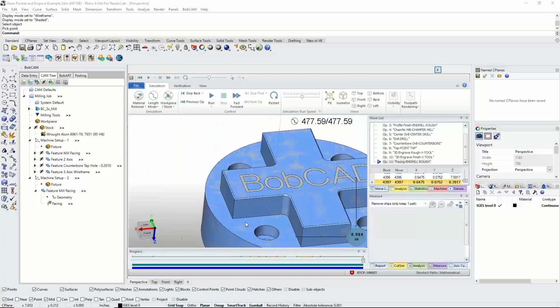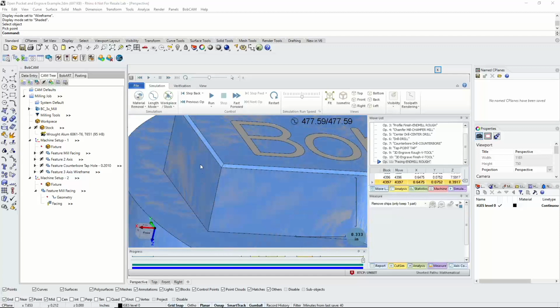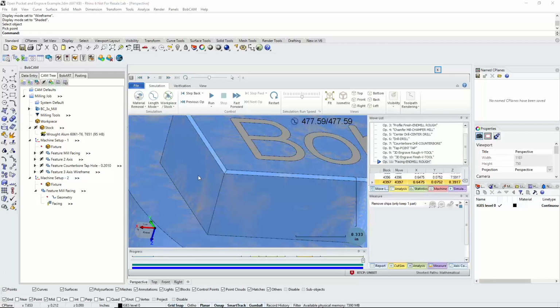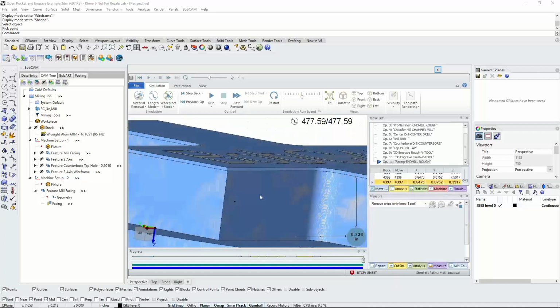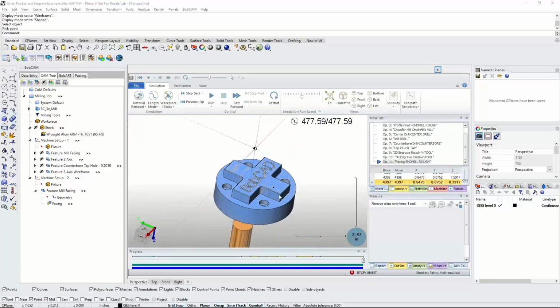The other thing to look at, though, is the sides of it, the walls. And we'll notice that there's both that blue color and the white color. And that basically comes down to the fact that the simulation is showing us 2 surfaces that are sitting flush with each other, sitting perfectly with each other. So it doesn't really know whether to show you the blue machined geometry or the white workpiece geometry. So that's a good sign. That's how we want our parts to come out finished. There are some other ways of checking inside the simulation if you're all to size.